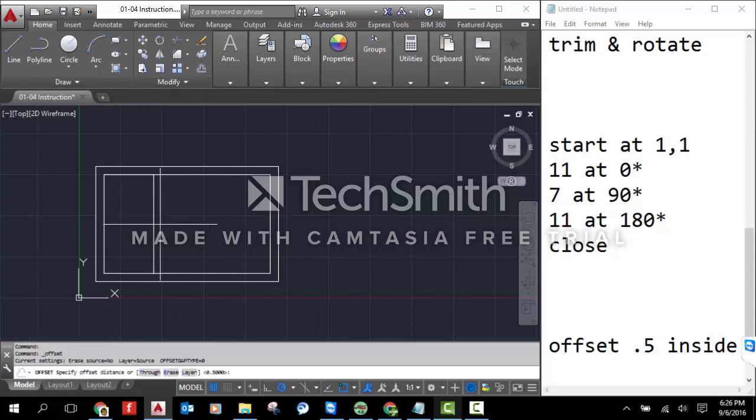We're going to offset this line 0.5, and move it over. Then we're going to do the same thing on the other side. So we're going to draw a line 3 inches in, draw it straight down, connect it. We just use the object snap for that. And then I'm going to offset this one. The distance again is 0.5, and we're taking it to the inside.